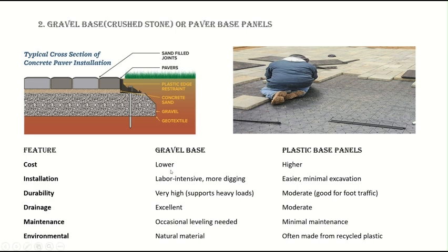The gravel base is basically cost efficient, right? Plastic-based panels are not. They are a higher price, but they will give you more convenience if you want to do it yourself. But if you want a professional company to do it, you should go with gravel base because it is heavier and can support heavy loads, so we don't have to worry about it in future. Occasional leveling is needed for the base that we're going to install, but that's not a big deal.